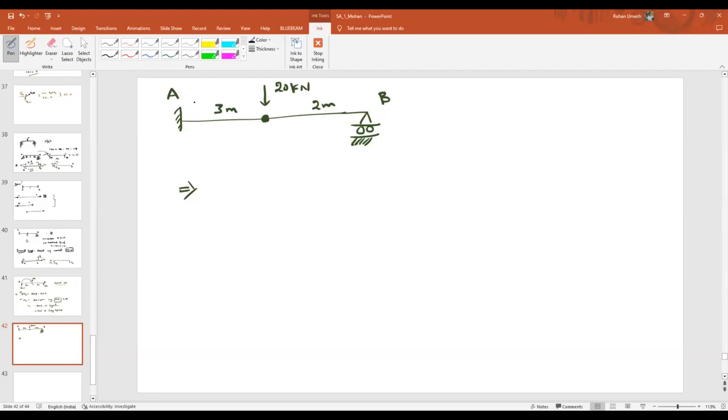but at the end of the day, you will end up with only 1. But as I am representing this as a vertical force, I will be happy if you consider only 2. What are they? Upward reaction RA and the moment. Let us say this is the unknown reaction at A, and an unknown moment at A. And here how many reactions will develop at B? Only one, sir. What is it? Unknown reaction at B.